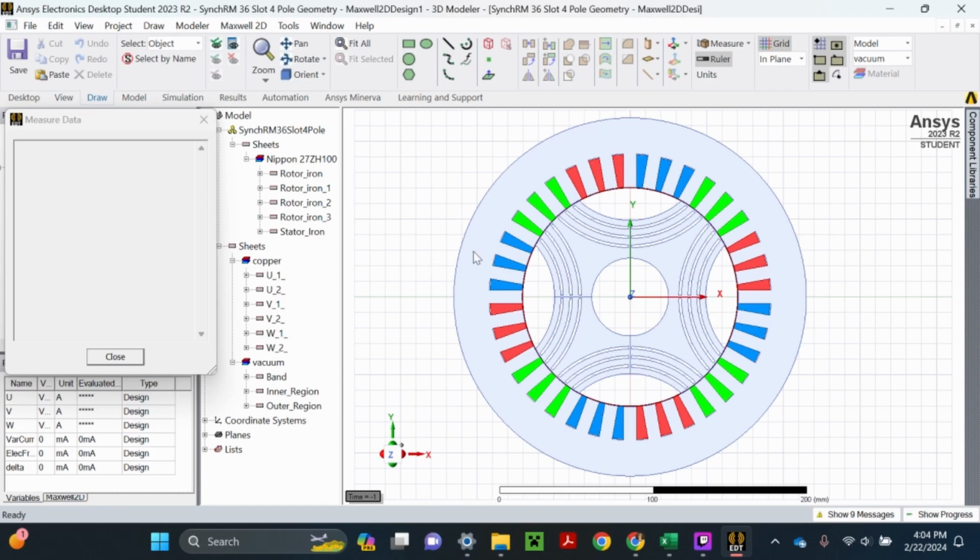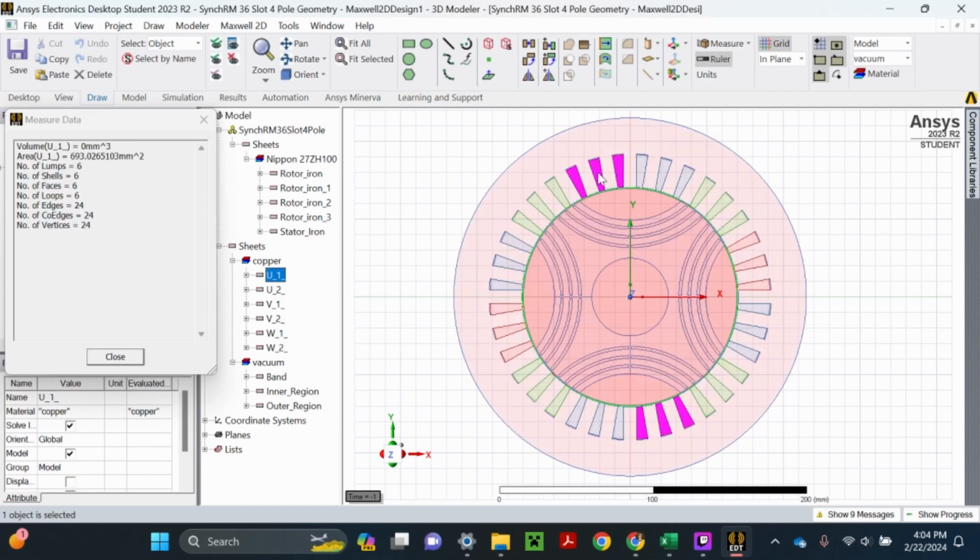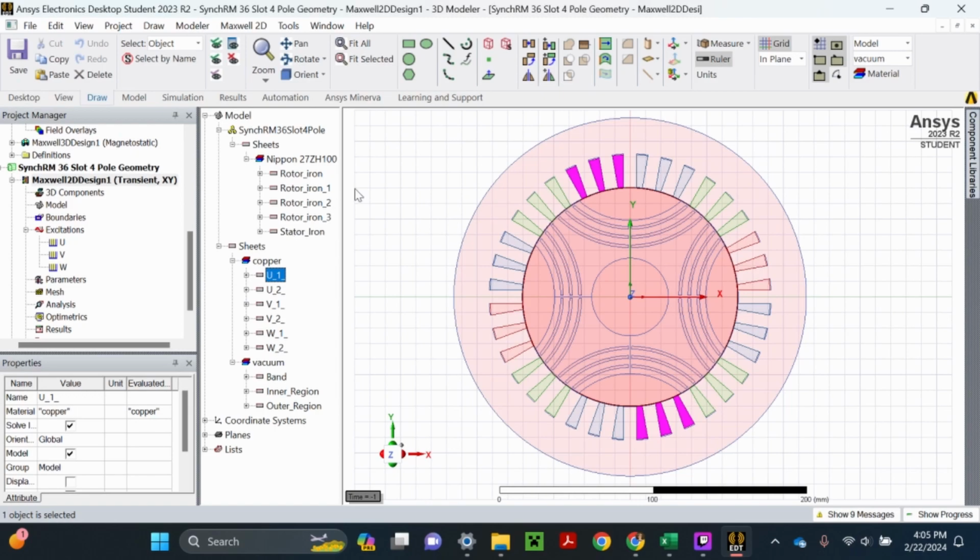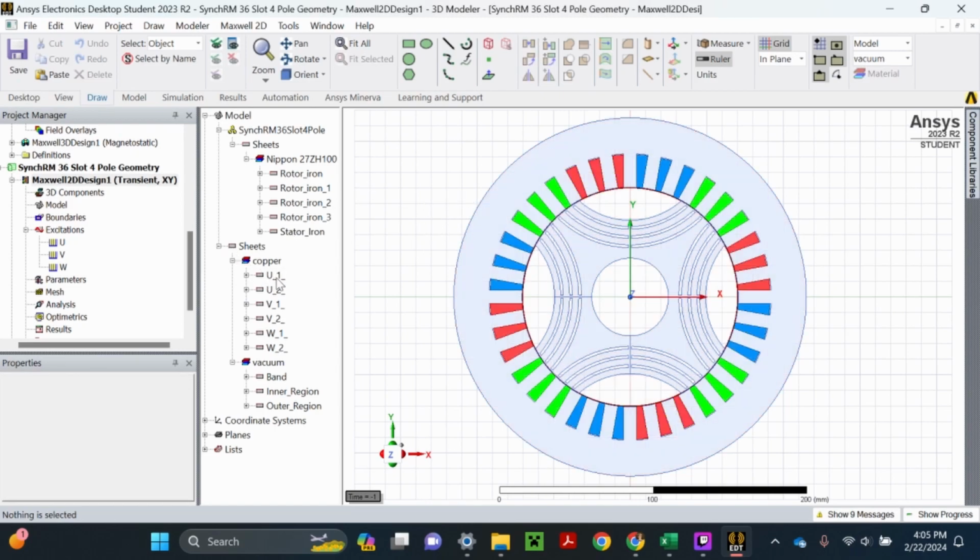And right now, I have all these windings as one solid object. And this was a question in class before, I think. And I think it is useful to unite all these slots so that it can just be one excitation, because I remember before for one of the examples we had to click each of these slots and then assign them to a phase.